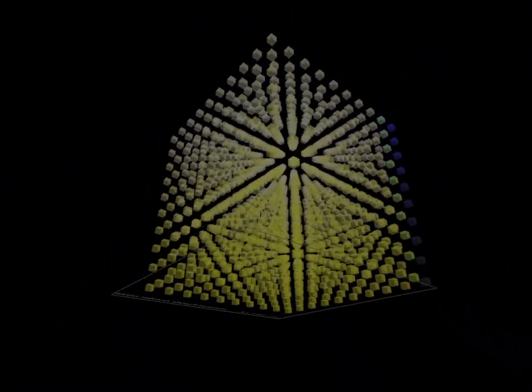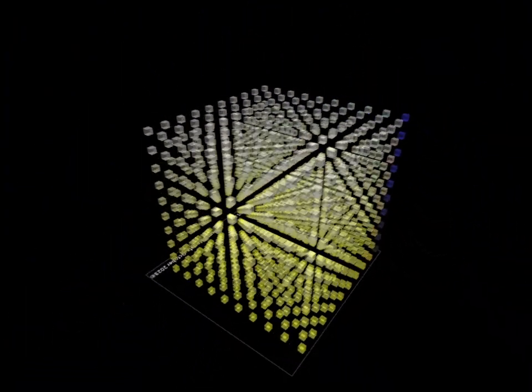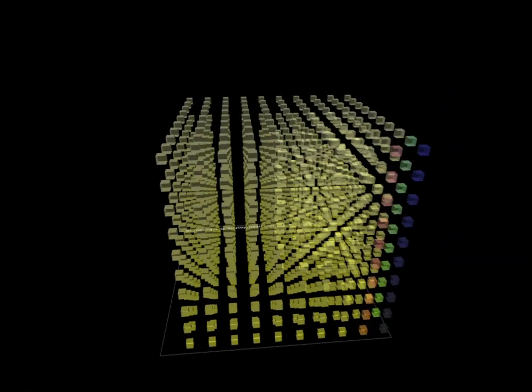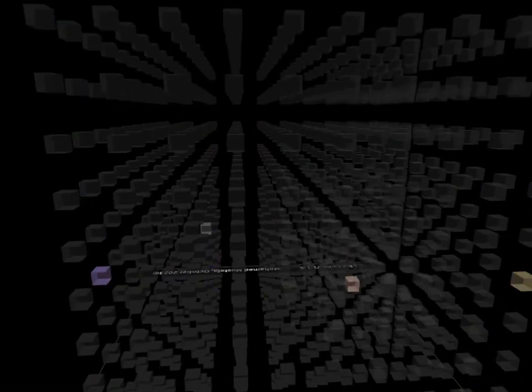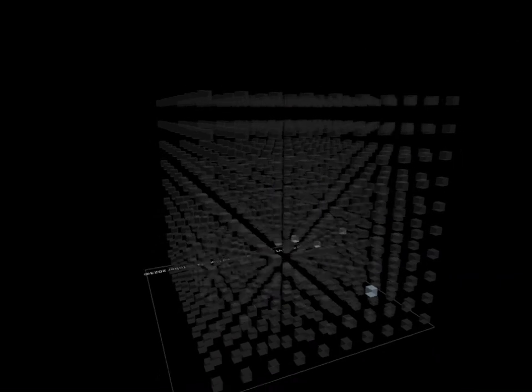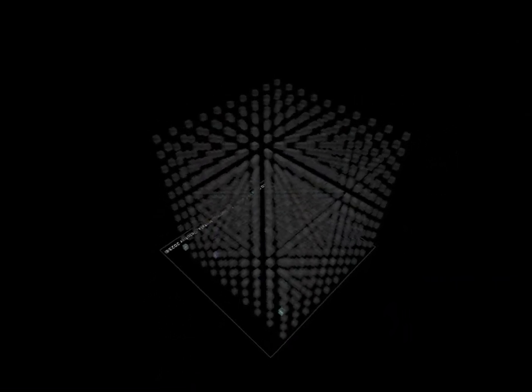With this setup, we only need 64 I/O ports for the anodes, plus 8, one for each layer, to control the LED cube. In the video, the process is slowed down enough for you to see it, then it runs faster and faster until the refresh rate is fast enough for the camera to catch the POV effect.